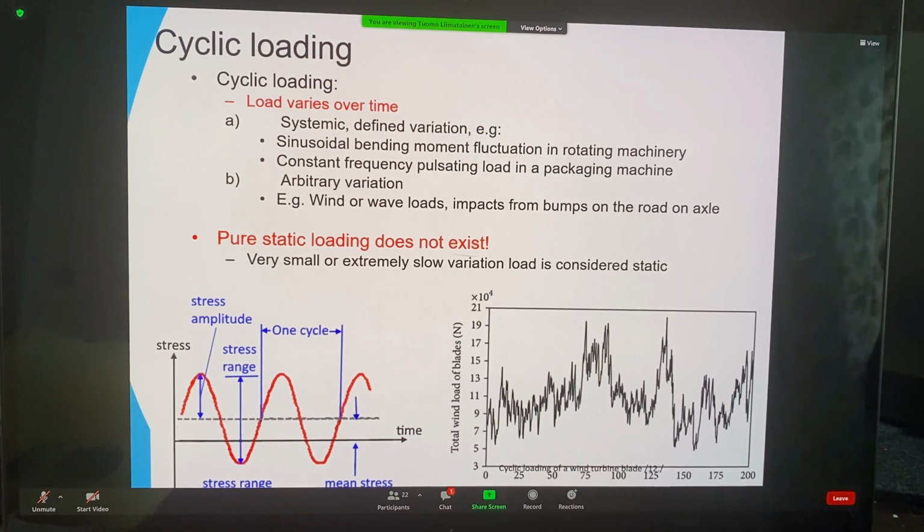If you have a mass load on a shaft, which is constantly bending the shaft downwards, and you rotate the shaft, that will cause the shaft itself to bend in different directions due to the rotation. The load stays in the same direction, but not in relation to the shaft. And that will cause a sinusoidal bending load in the shaft.